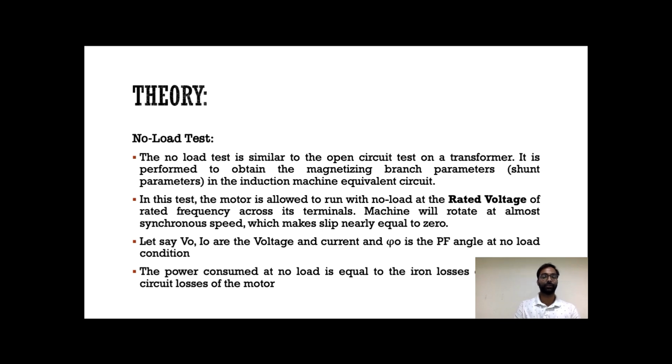Coming to the theory, first we will discuss the no load test, then we will go to the block rotor test. For the no load test, the first question that comes to our mind is why it is called no load test. Since this test is performed at the no load condition of the induction motor, that's why it is termed as no load test. And it is just similar to the open circuit test of the transformer.